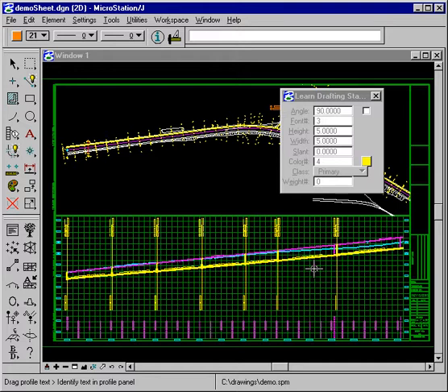your plan should look, either just for everything you draw, or you can also teach it a different drafting standard for different MicroStation workspaces, so that you may have one drafting standard for one client, and any project you do for that client will look one way, yet you have a different drafting standard for another client. So we'll use the Learn Drafting Standards to change the way this profile panel looks.